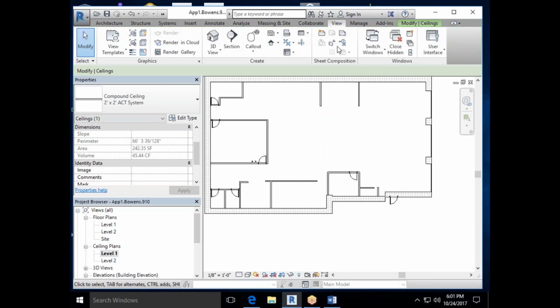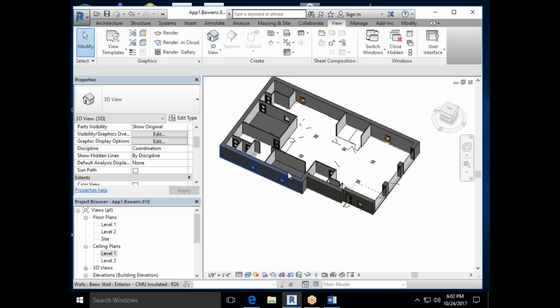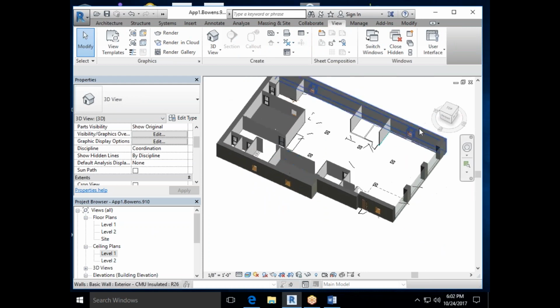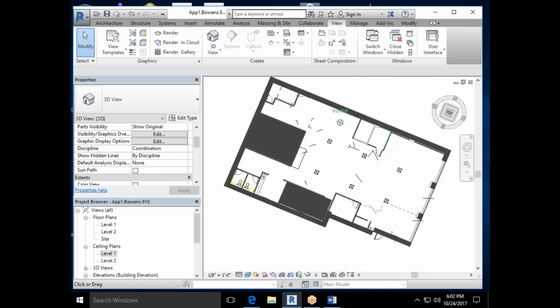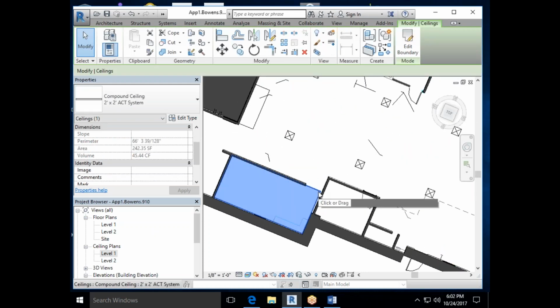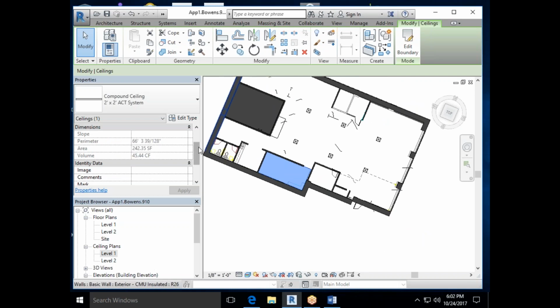Okay, so then if I go into my view and my 3D view, it keeps drawing them at the floor level. So if I check it and I say I've got this height from offset of level, let me see what level it's saying, because that would help me. From level. Allison? Do you think it would need to be a negative 10, so instead of going down 10 to the floor, it would be going up 10?